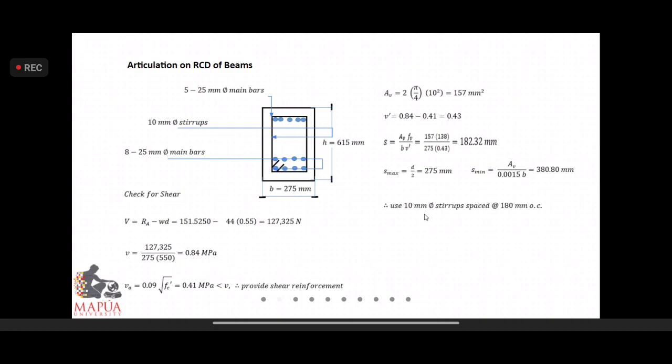And the place or the setup wherein we're going to place the stirrups will be based on the similar triangle. So this is equal to 2.8937 meters, as indicated in our shear diagram. This will be V prime. So in essence, we can compute for X of 1, which is equal to 1.48 meters.